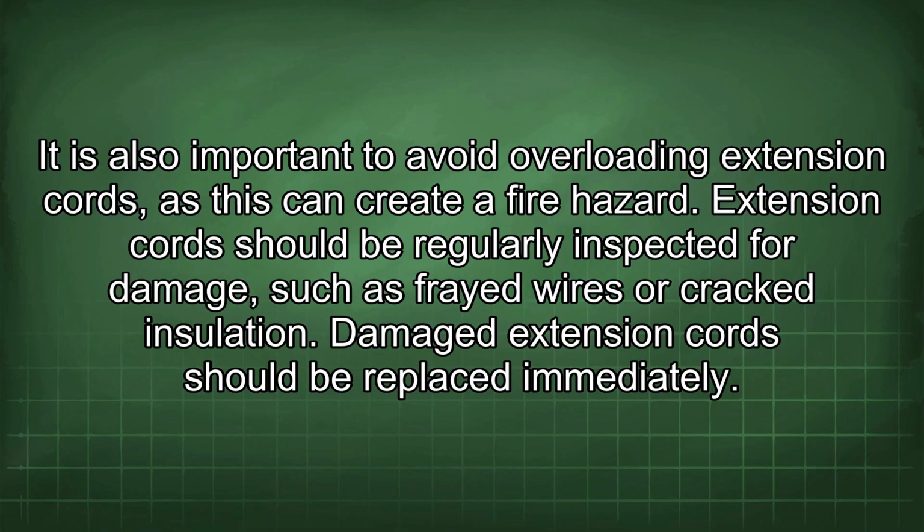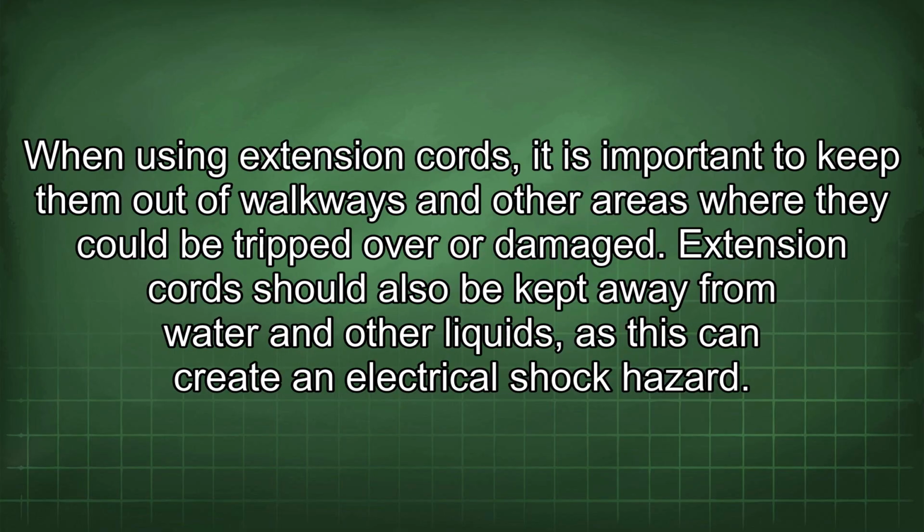Extension cords should be regularly inspected for damage, such as frayed wires or cracked insulation. Damaged extension cords should be replaced immediately. When using extension cords, it is important to keep them out of walkways and other areas where they could be tripped over or damaged. Extension cords should also be kept away from water and other liquids, as this can create an electrical shock hazard.